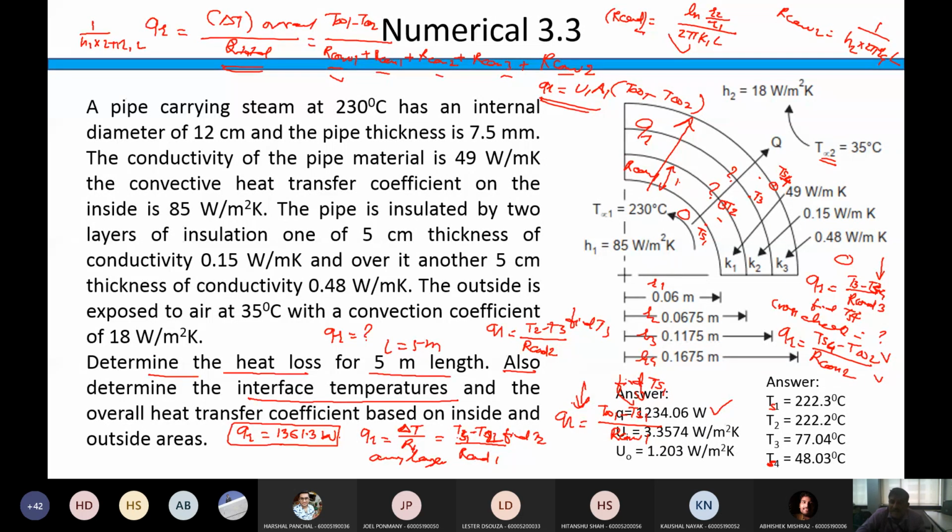Now, if you look at the middle layer, whose thermal conductivity is 0.15 watt per meter K, see the temperature drop from 222.2 degrees C, all the temperature is dropping directly to 77 degrees. Now, why does this happen? Because the thermal conductivity of that layer is very low, so it is offering very high resistance to heat, or not? Yes sir. Fine. Now, shall I go ahead?